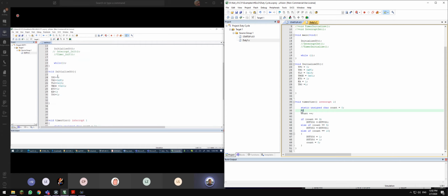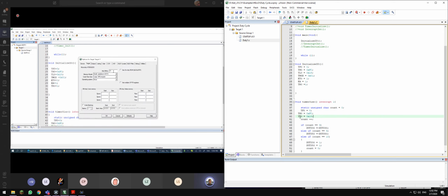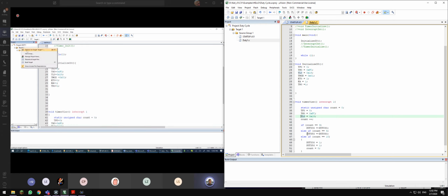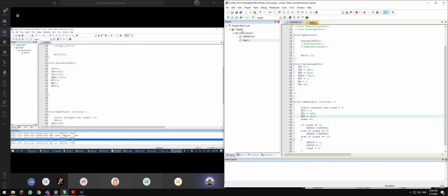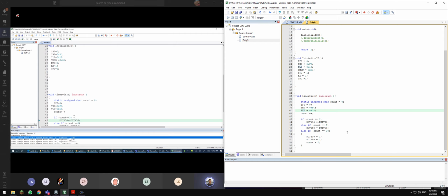Okay, let's compile it. 30% and 50% duty cycle will be generated. Of course, I will put the option here. I'm using 12 megahertz. Just right click here, target, right click, option 12 megahertz. So I compile this. Hope there's no error. Oh dear, why got error? Why so many errors? Where is the error? If count is equal, what's wrong with this? Count equal duty, so it's correct.